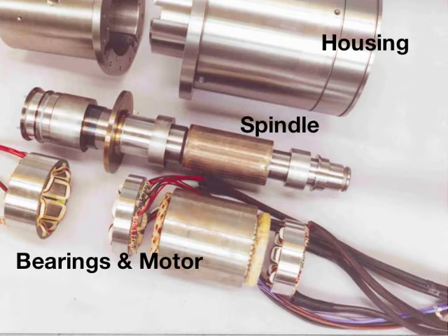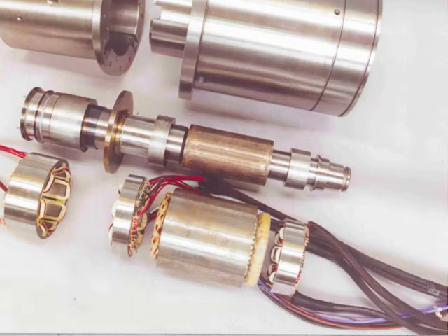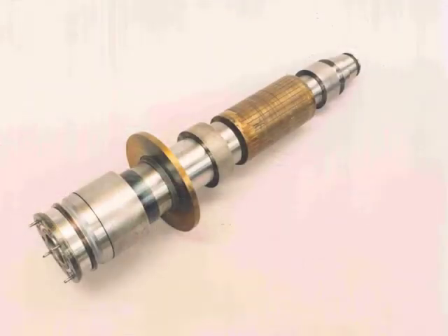To accomplish this, there were 3 radial bearings to control the radial motion of the spindle at different locations, and 1 axial bearing to control its motion along its axis. These bearings are shown at the bottom of the photograph, along with the stator of the motor. Here is the spindle itself. This is the part which we've magnetically suspended, and this is the part of interest to us from the point of view of poles and zeros.